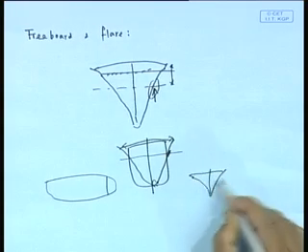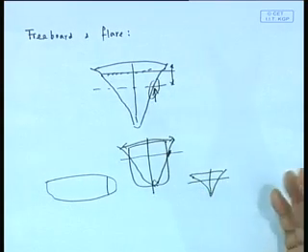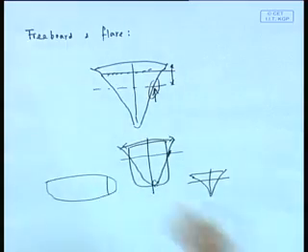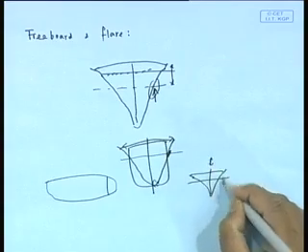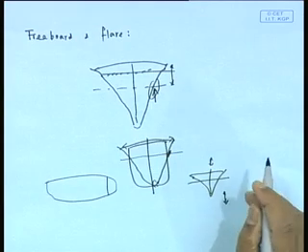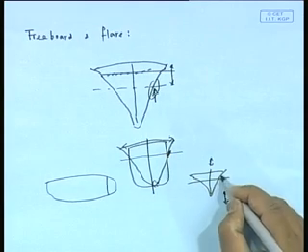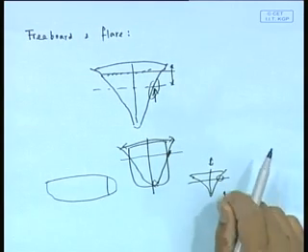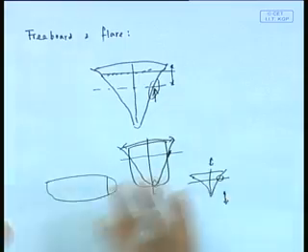If you want to have large flare, you will find most of the aircraft carriers have a large flare. But if you have large flare, then you must make sure that the ship has lower vertical motions, because otherwise they are going to have large slamming here. So therefore, it's a question of a combination. Bottom flare you can afford to have large, provided the vertical accelerations are small. Because if it is small, then load is going to be small.